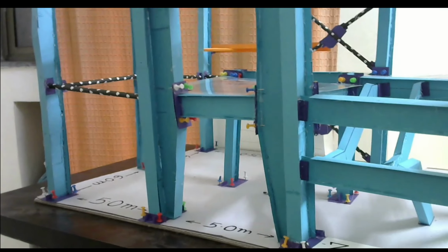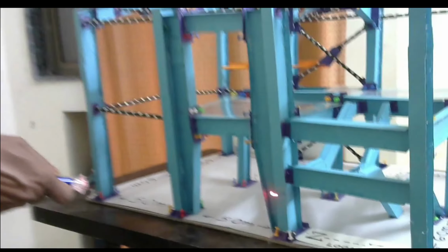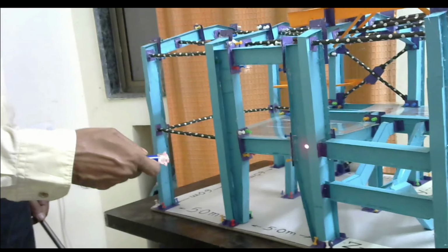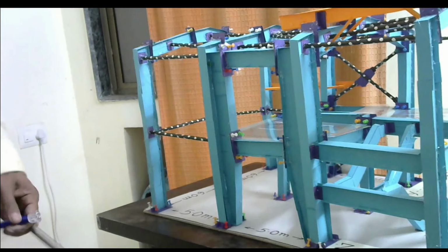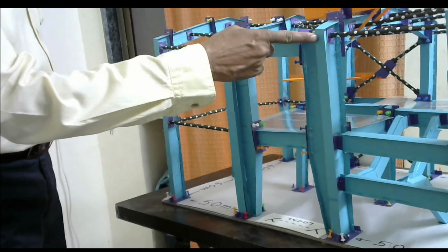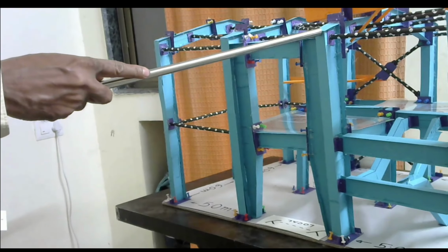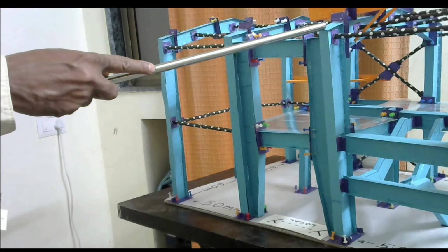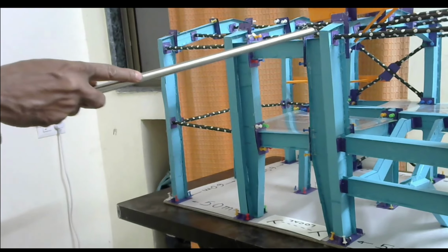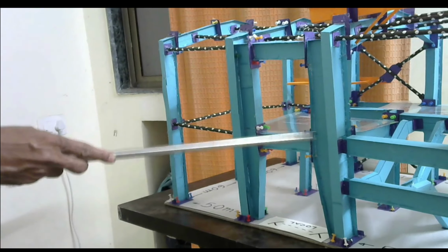Now why 3 meter? Because the main frame is a sway frame. Then how can we take 3 meter? I told you, for this portal frame when we consider the YY direction, this main frame is actually acting as a portal frame. So for a practical purpose, we can assume this main frame is extending this portal frame about the YY direction. So this is 3 meter.